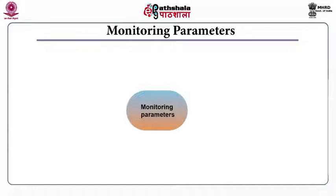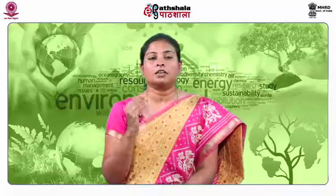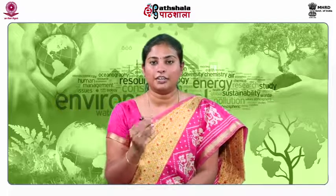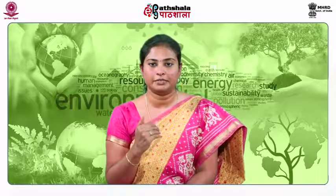Now, let us discuss the various monitoring parameters to facilitate faster waste degradation in the landfill bioreactor. The different monitoring parameters are moisture, temperature, gas flow and quality, waste density and settlement, leachate yield, quantity, quality and leachate flux. Continuous monitoring should be done for the landfill bioreactors so that operational failures can be minimized.